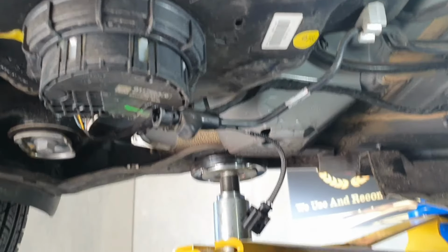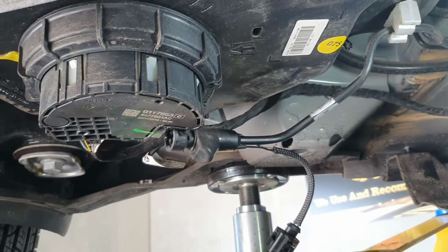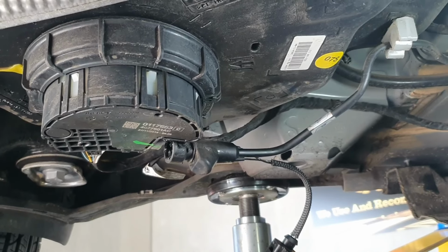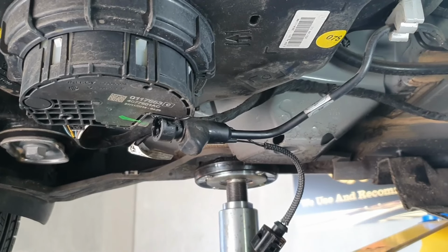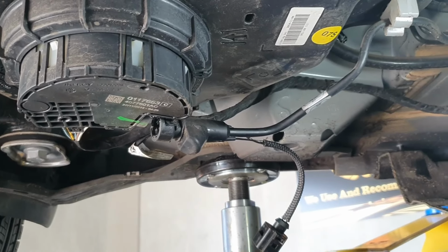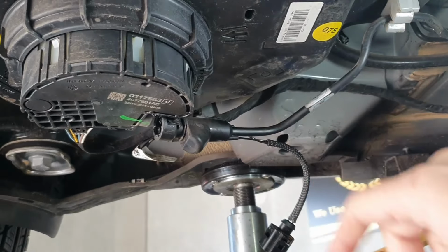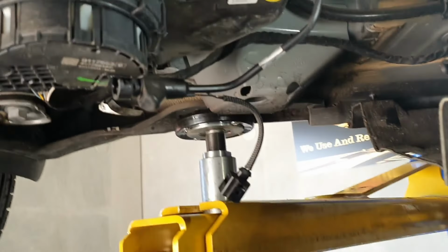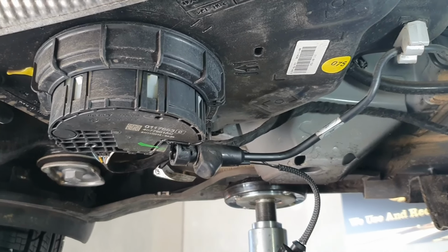Just a side note guys, I just pulled this end off. What's supposed to happen on these VAG motors is that when the engine is turned off, the pump is supposed to reverse the flow and take the AdBlue back out of the line and into the tank. That way, under cold conditions, it stops the AdBlue from freezing. So you can disconnect this line. We put a drain tray anyway, just in case, but we didn't need it. So that's the theory behind it. Thought I'd let you know that.